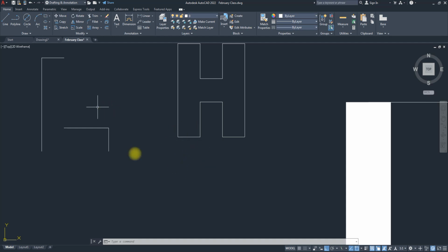So let's assume I don't know the length of this edge, that base, but I know that the circle should pass through from this point to this point. Then 2 points is the best option to choose. I'll just come here, go to 2 points, and I click on this edge, and come to this next edge, click, it creates that. That's using 2 points.